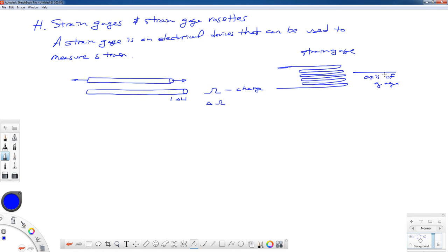Another interesting application of strain gauges is on not only truck stop scales and maybe grocery store scales, but if you've ever seen one of these laptops that have a little post sticking up for a mouse, and it's a mouse button, and you push it forward and the mouse cursor moves one way and you pull it back, well, that is a strain gauged sensor as well, and it can detect which way you're bending that little post. Same idea is used in modern aircraft for the flight stick. You bend it one way or the other, and it senses which way the pilot is trying to maneuver the aircraft, and it applies certain signals accordingly.